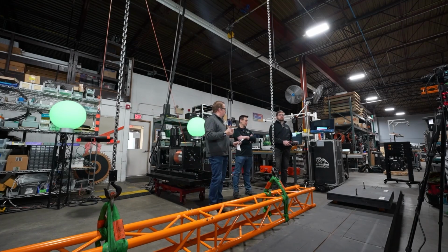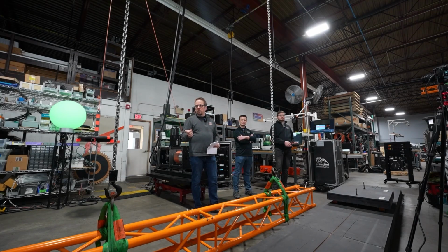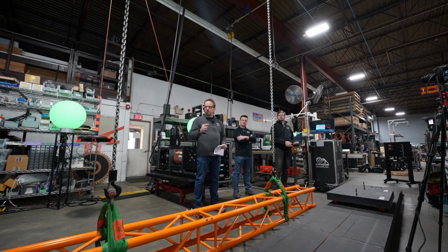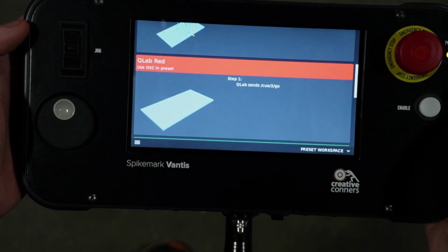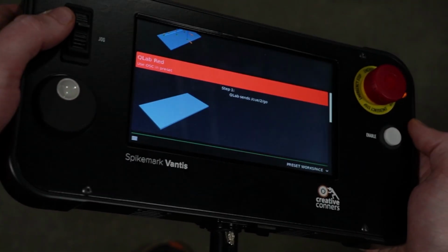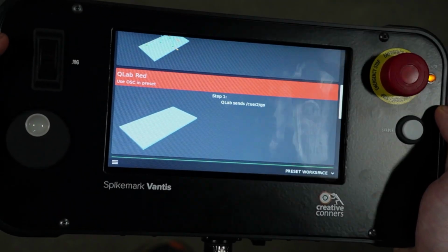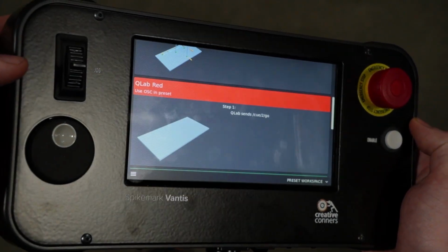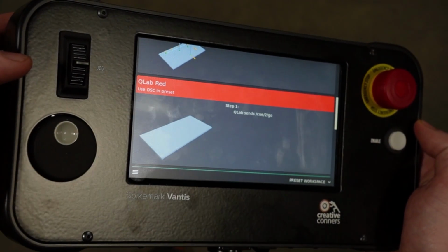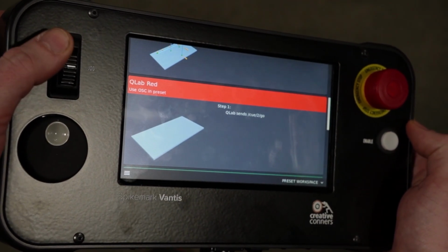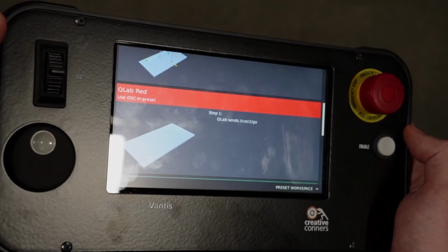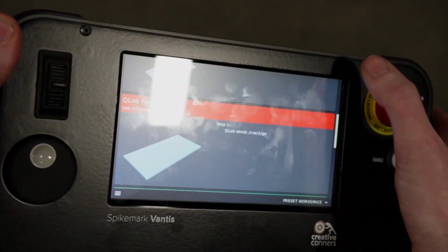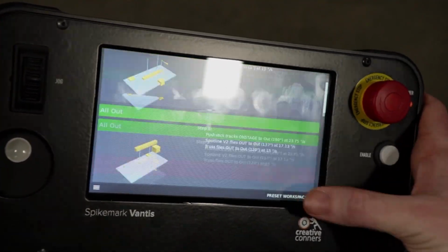And then for jogging, what was the other part of the question? I think that probably answers it. But if we want another close-up, for jogging we get that little paddle on the left that you press in conjunction with the enable button. And for any of the recall, that joystick there is a variable speed joystick on his left thumb. And so if you want to maybe jump back to jog.